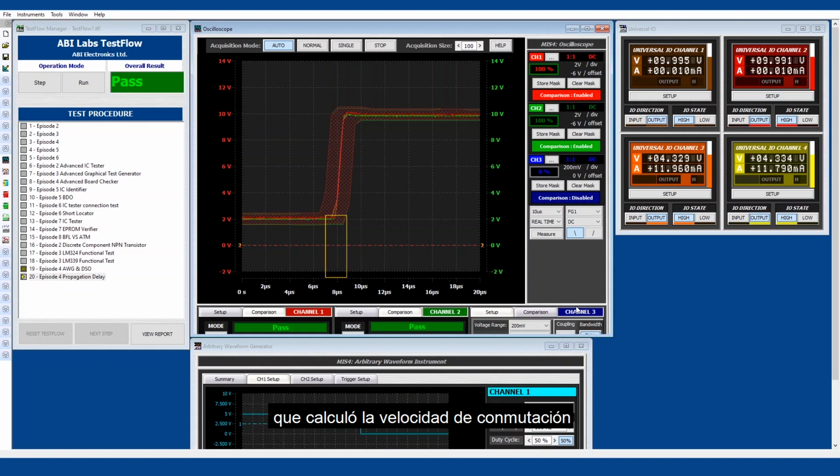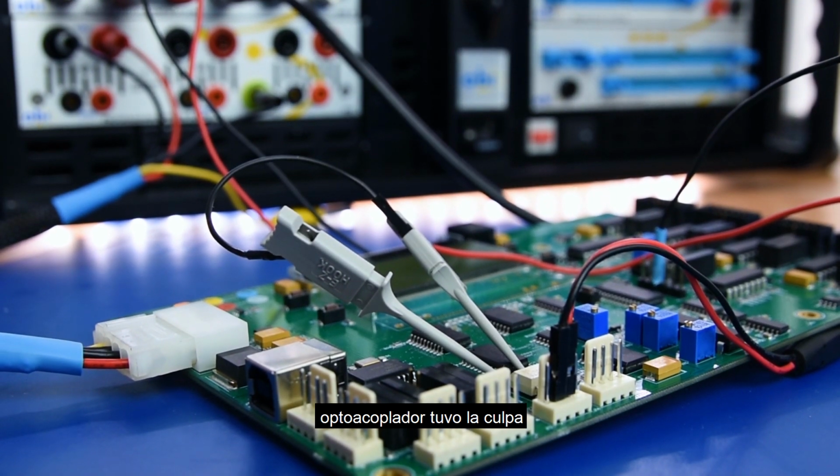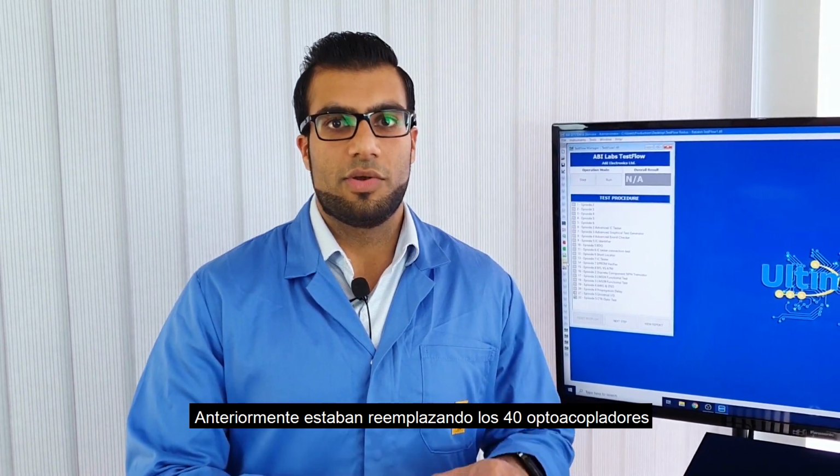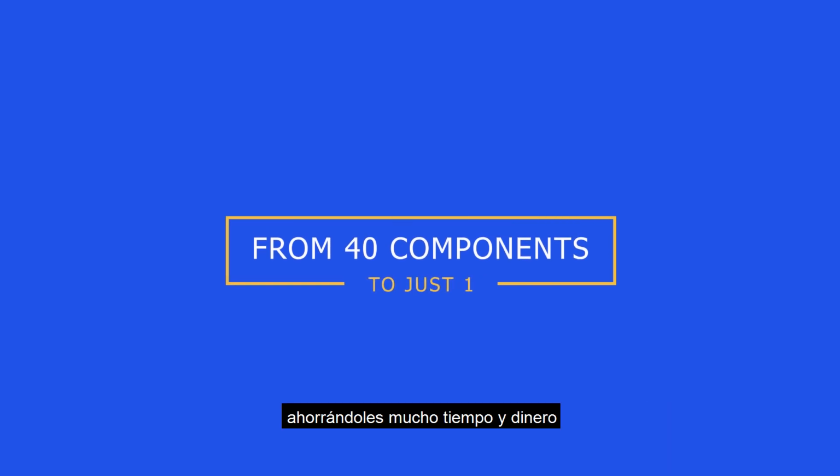They worked out the switching speed, the propagation delay of the optocoupler, which allowed them to find out which actual optocoupler was at fault. They had previously been replacing all 40 optocouplers, but then they minimized this all the way down to the actual optocoupler that was failing, saving them a lot of time and money.